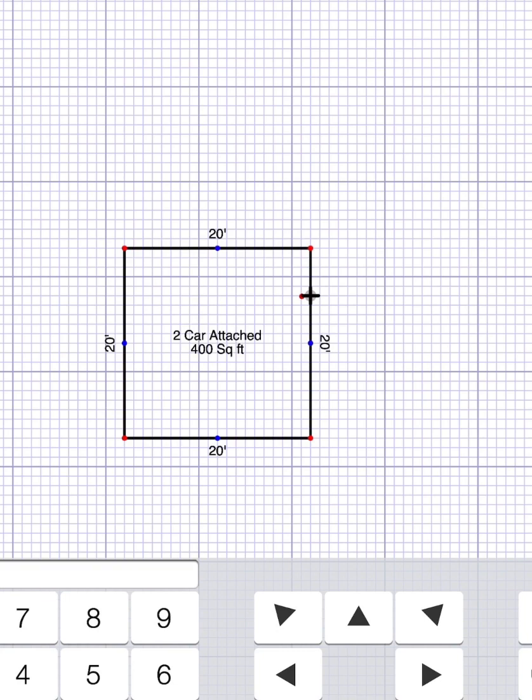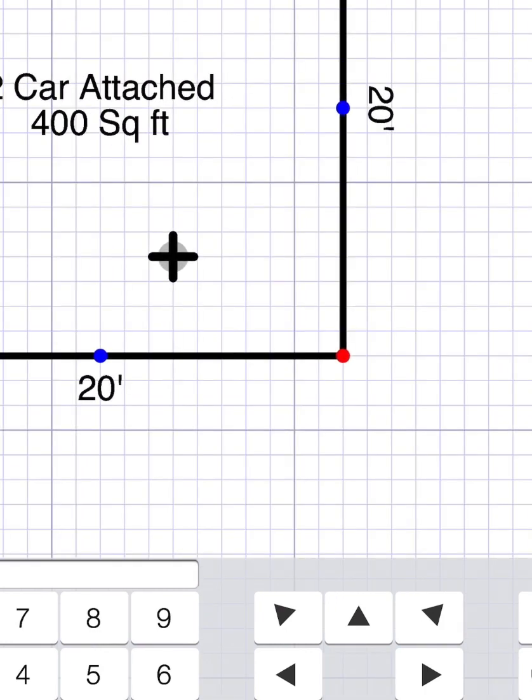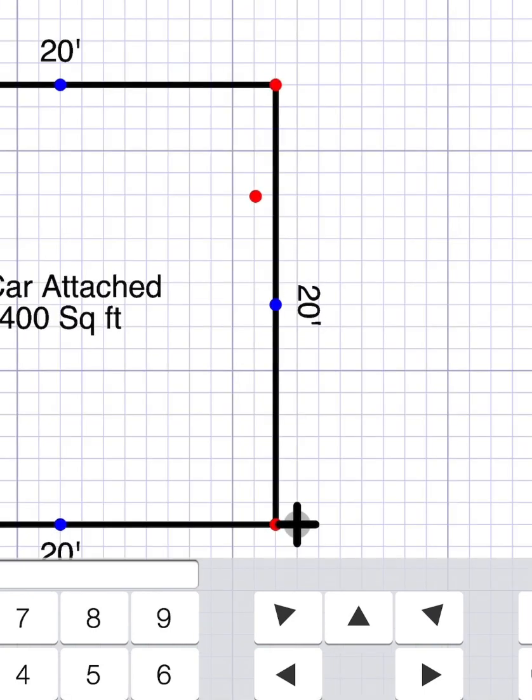So what I'll usually do is I'll have my laser measurement tool. I'll start from the front of the garage, which is like over here, right there. And then I'll use my laser measurement tool here. I'll point it at the wall, where the front door is over here. And then I'll get some measurement. So it's probably like 16 feet here.